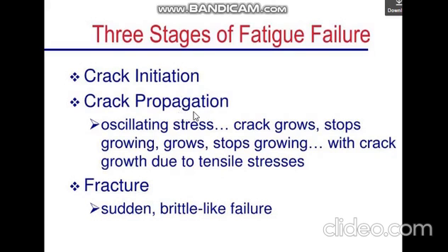Crack propagation means crack growing. Oscillating stress is repeatedly going up and down like a sinusoidal wave. Crack grows and stops growing. Crack grows, stops growing, then grows again, stops growing. Crack growth is due to tensile stresses. You see, it is opening its mouth, closing its mouth, opening. When it is in compression, it closes its mouth. When it is in tension, it opens its mouth. When it is in compression, it closes its mouth.